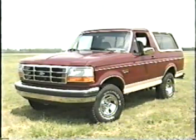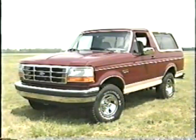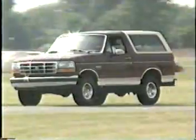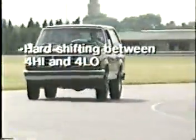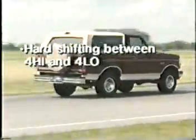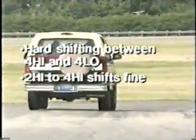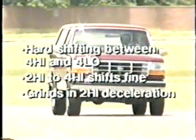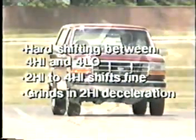This 4x4 was towed in because it jumped out of 4 low and started making grinding noises. Now it won't shift at all. During your road test, you discover that the four-wheel drive shift lever is binding between 4 high and 4 low, even with the engine off. With effort, you finally work it into 4 high. Between 4 high and 2 high, it shifts fine. As you drive off in two-wheel drive and you decelerate, there's a pop and the grinding noise starts again.